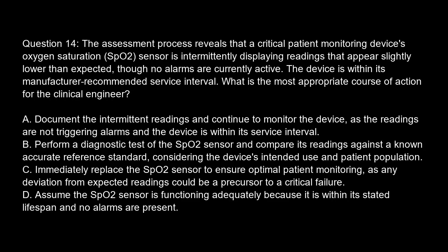What is the most appropriate course of action for the clinical engineer? Option A. Document the intermittent readings and continue to monitor the device, as the readings are not triggering alarms and the device is within its service interval. Option B. Perform a diagnostic test of the SpO2 sensor and compare its readings against a known accurate reference standard, considering the device's intended use and patient population.